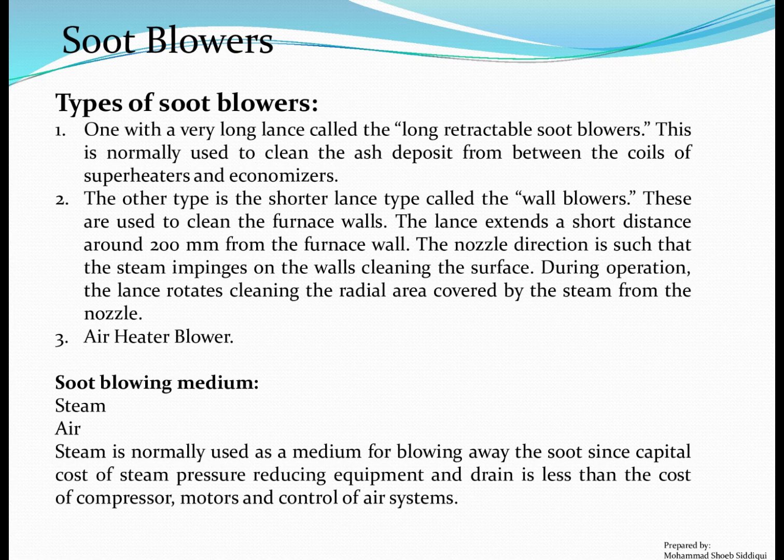The lance extends a short distance, around 200 millimeters, from the furnace wall. The nozzle direction is such that the steam impinges on the walls, cleaning the surface. During operation, the lance rotates, cleaning the radial area covered by the steam from the nozzle. 3. Air heater blower.